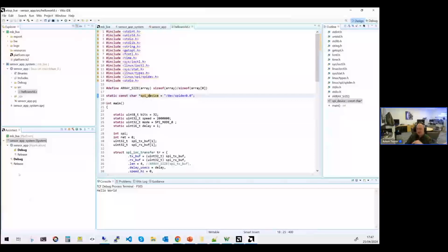Yeah. So this is the one benefit. I didn't put a sysroot in this. You can define the sysroot if you want, but because this is just using really standard basic libraries, it's all within the ARM GCC toolchain that's installed with Vitis. And Jason, yeah, it's much easier to do this because now you can single step in, and do all sorts of things, inspection, watching, and it's just like software. It's accessed over JTAG, but it's not sat on the bench next to you. It happens to be in a lab or somewhere.